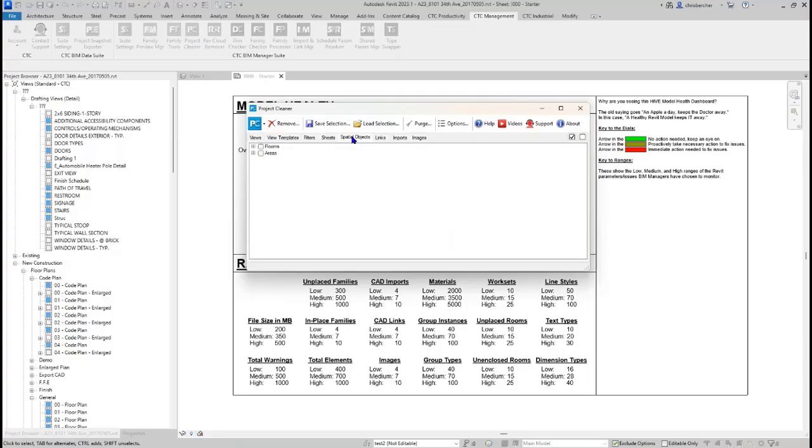keep. If you're inheriting projects, chances are there's going to be unplaced rooms, areas, or spaces, or there's some redundancy, or you just want a flat start over because they didn't match your standard. You can purge all that out in one shot, or again, go through and pick and choose what you want to work with, what you don't want to work with. Okay, pretty slick little workflow for getting rid of those really quickly. Yes, you can do it through the schedule, but this way takes care of that as well.